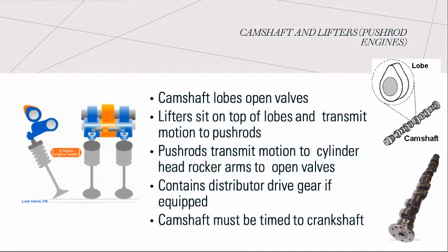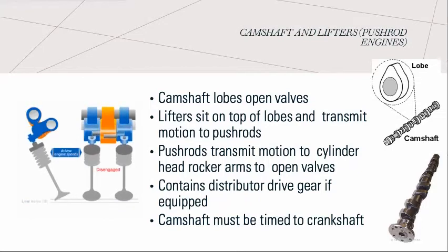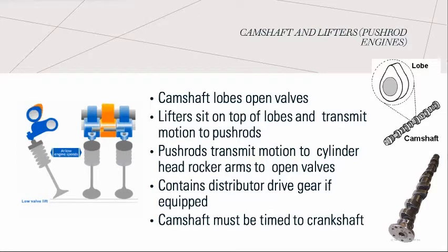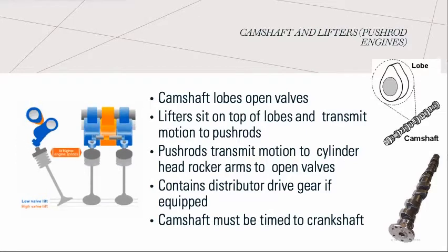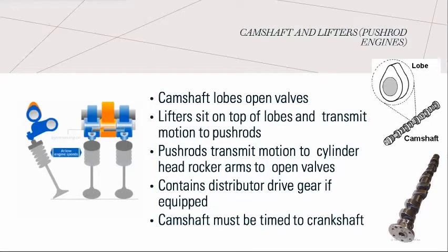A valve needs a system to make it open and close. Control of the valve is accomplished through the use of cams on a common shaft. A cam is an egg-shaped piece, the lobe, mounted on the camshaft, and the egg shape of the cam lobe is designed to lift the valve open, hold it open, and let it close. The camshaft is timed to the rotation of the crankshaft to ensure that the valve opens at the correct position of the piston. Timing the valve opening to the piston is critical to ensure proper power output and low emission